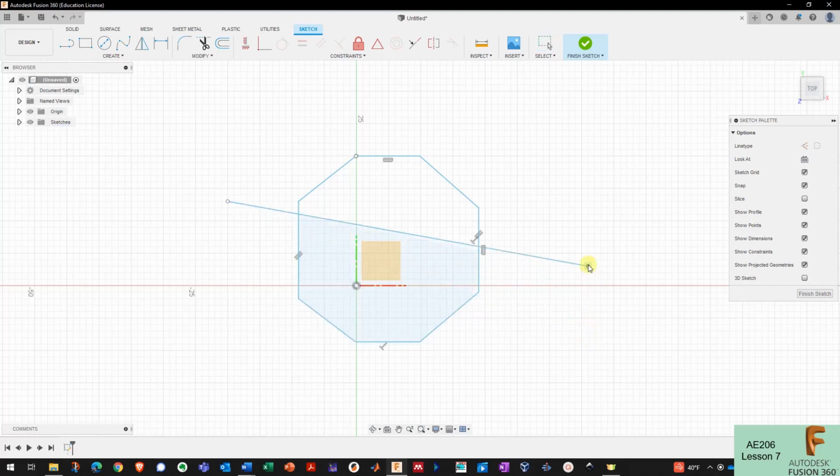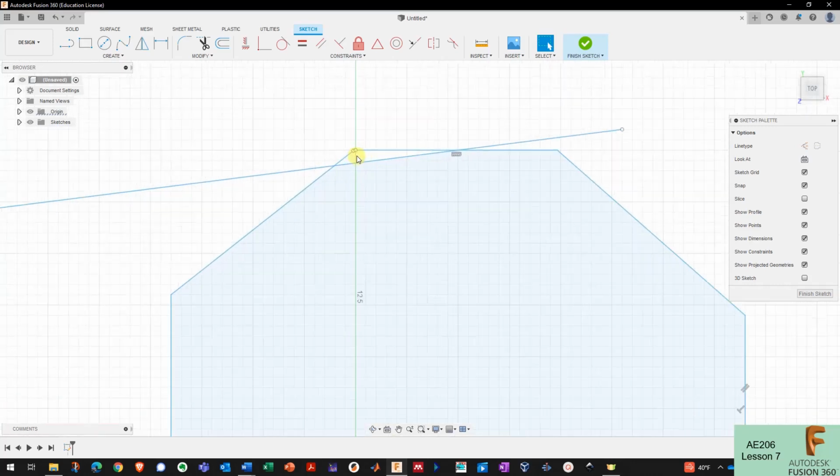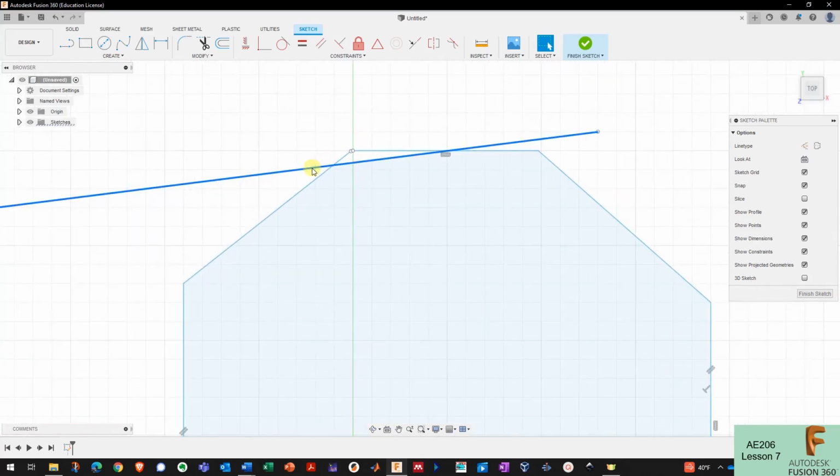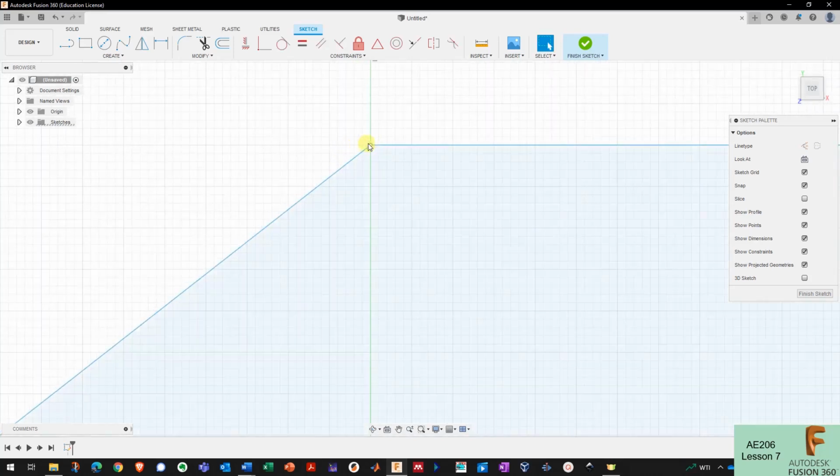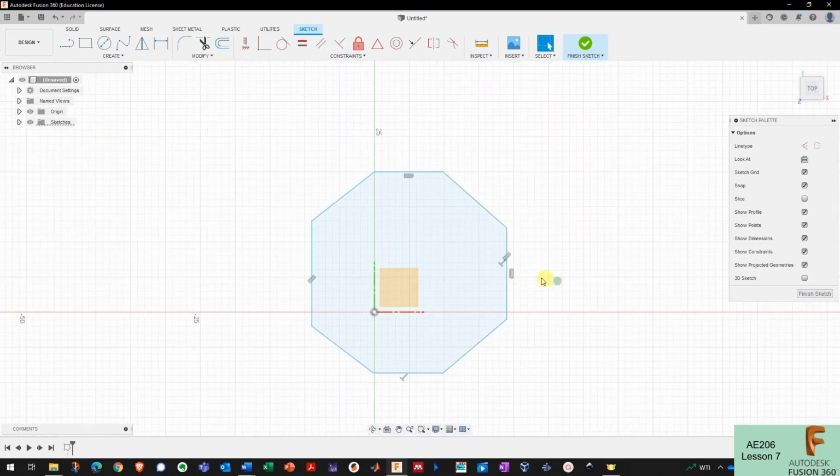I can move this line around to try to narrow down where the sketch is not closed. If I do it like this, what I'll figure out is that this entire portion of the sketch and all of the points on it are closed, and the offending point is up here in the part of the sketch that's not closed.